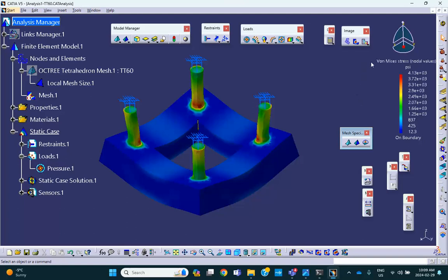Now, you just have to make sure that whatever you get here does not go below or above the yield strength. Otherwise, the analysis would have been completely nonsense. It's very easy to generate good-looking, meaningless things, colors. Okay, so let me save this thing.